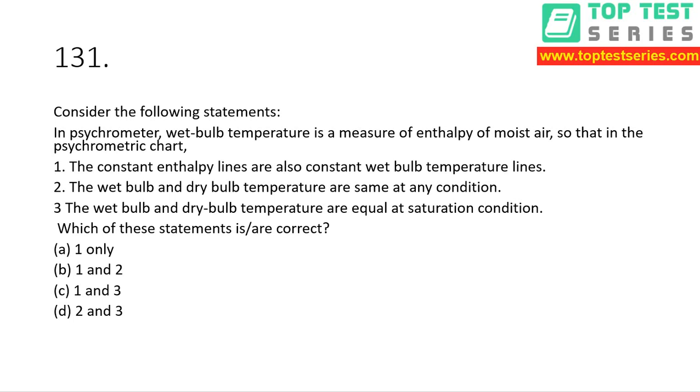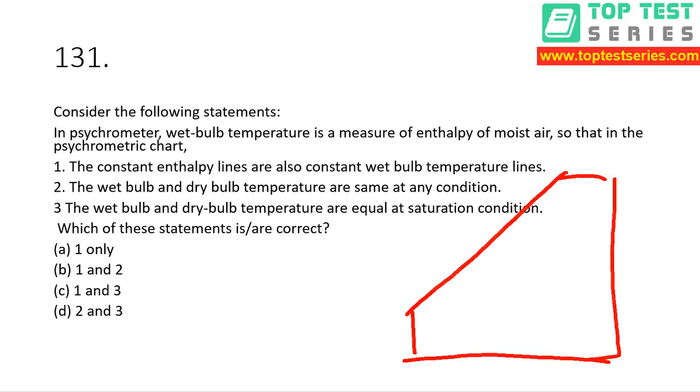My dear, this is again a good question. Only at one condition, my dear, it is not possible. But for this, we have to draw the diagram. That is what? Psychrometric chart, right? This will be like this curve, right? It is saying constant enthalpy lines are also called, yes. Just right now we have gone through this, my dear. In case of evaporative cooling, whenever going from 1 to 2 condition, we said that WBT is equal to enthalpy. That means this one is correct.